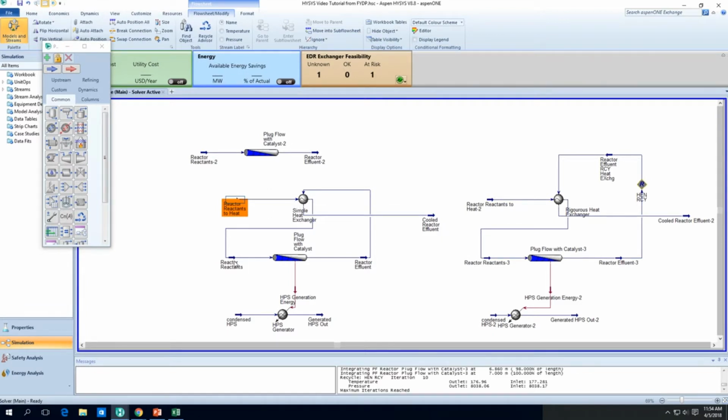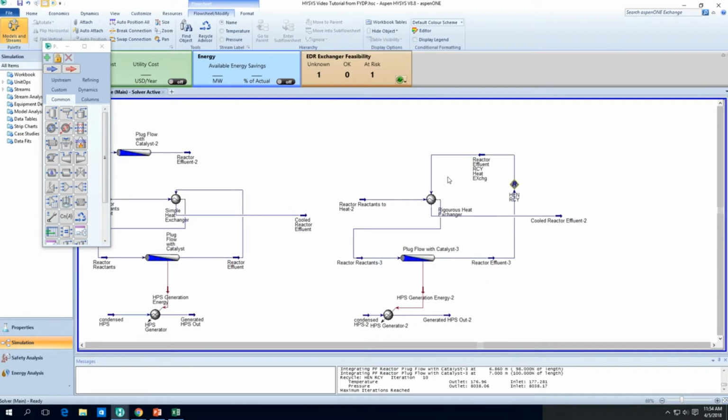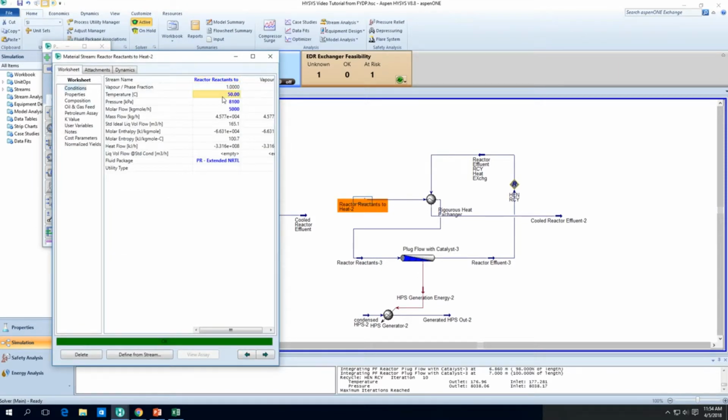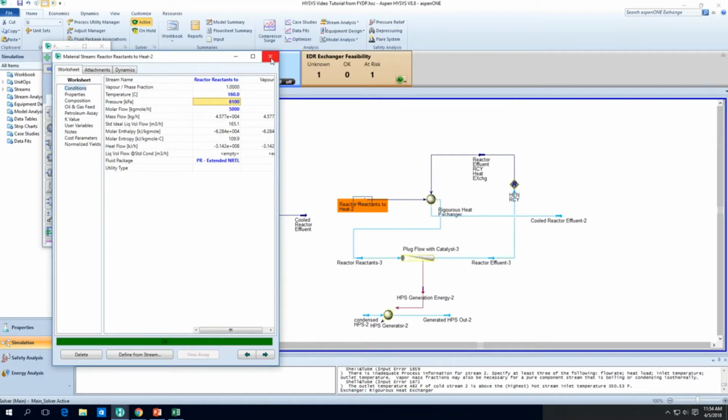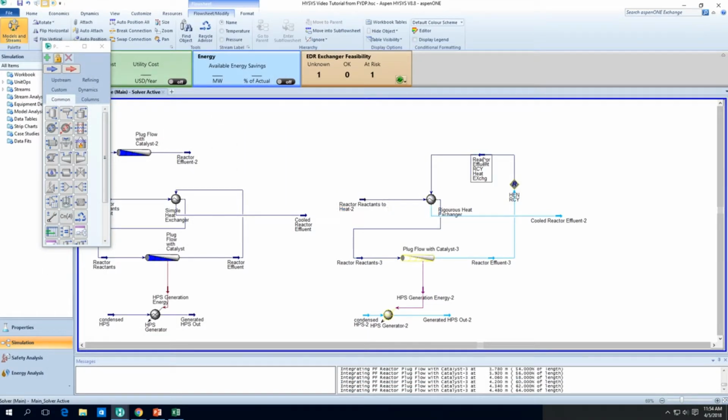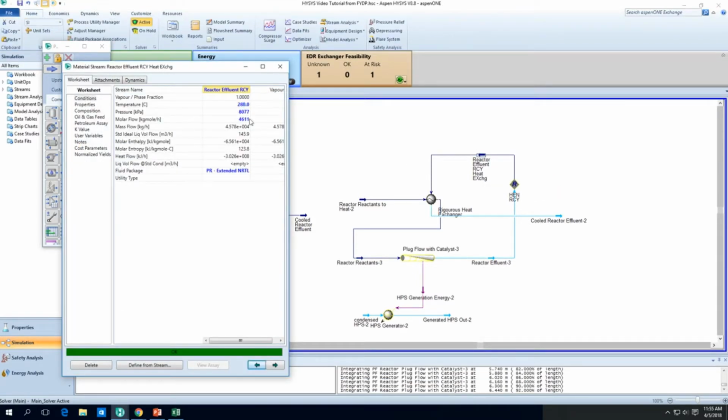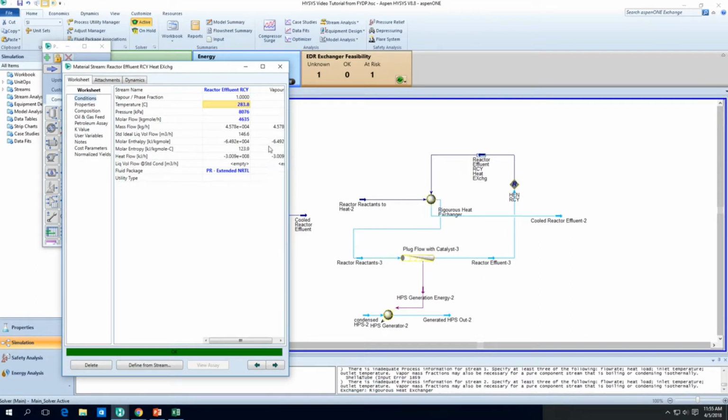Okay, we'll see whether it works. So the outlet stream should be about 186.5, where the cooled reactor effluent is. So let's just try that. 186, oh no, 160. And there you go. The thing is going to iterate again. So the temperature is rising. As you can see, the outlet stream temperature has gone back up to 280 degrees C. And it's gone back up a little high, in fact. Well, we'll just let the recycle stream do its job.